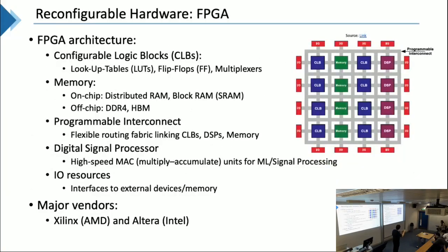So this is the compute architecture of FPGA. You can see the key component is, first, this CLB, which is basically a lookup table. You can reconfigure this CLB to any logic you want. You also have this memory, and this DSP. For example, you can use this DSP to do high-speed multiplication or addition. The idea of FPGA is they put all this general reconfigurable fabric, different memory and DSP, and use the idea called programmable interconnect, which means you can connect any CLB to any DSP to any memory.